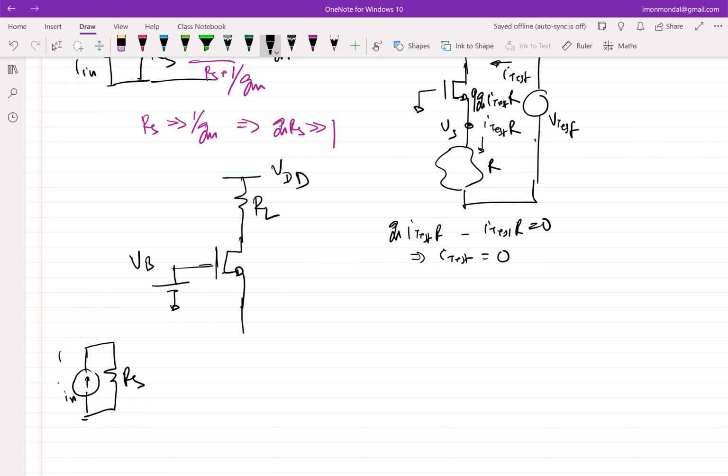And incrementally, I was planning to connect these two nodes, right? But if I in is an incremental current, that is, it has 0 DC value, then I cannot do that. Let's assume I in is a sinusoidal current source. Then if I connect it directly there, the transistor will not get biased. So I need to bias the transistor, which means I cannot directly connect it.